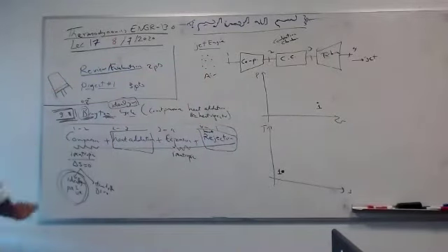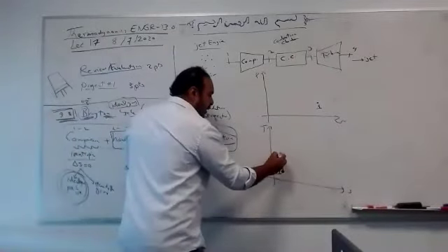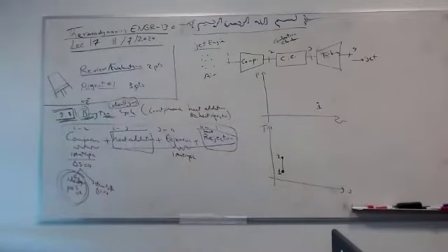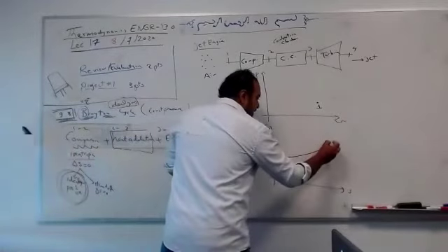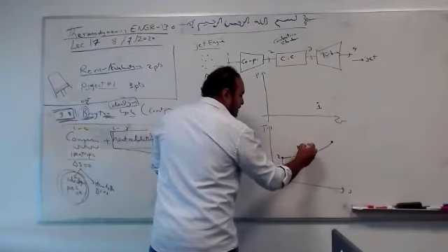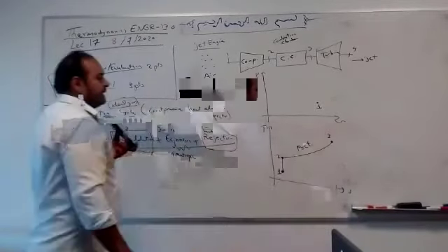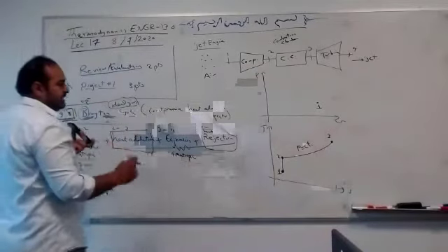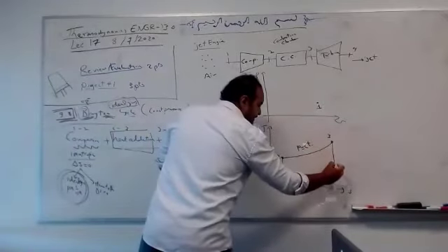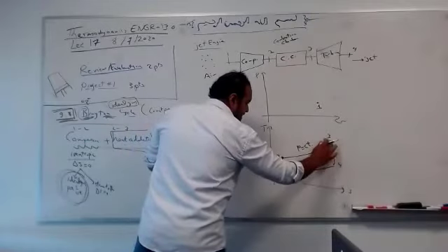So we're gonna compress. Isentropic, constant entropy. Here is so clear, vertically. In all of the cases, 1 to 2 is vertical. Heat addition, constant pressure. So we're gonna have something like this. Like who? Diesel. Diesel was constant pressure heat addition. Then we're gonna have turbine, which is here, isentropic, vertically. Something like this.